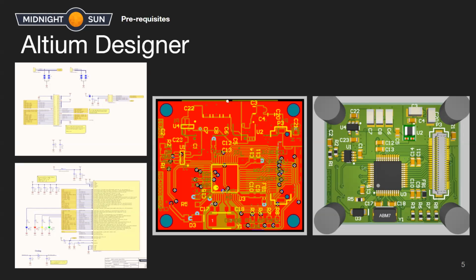Usually, you don't want your board to be super, super big, so you try to house all your components as tightly as possible. There's of course a lot that goes into it, like signal traces. You don't want them to go too long, but most traces it's okay. Some traces need to be a lot thicker because traces, by the way, are basically wires. So when you have a copper wire connecting a resistor to a battery, that wire is a trace. It's like a layer of copper in the board. For example, if you have really high voltage and really low resistance, it's a lot of current, you need to make your traces thicker.